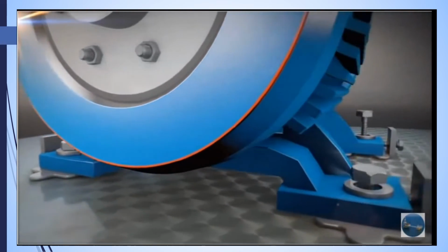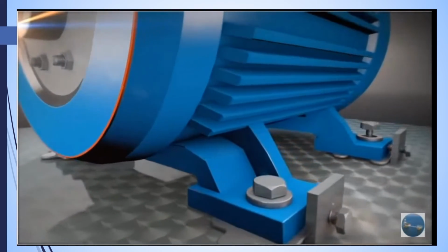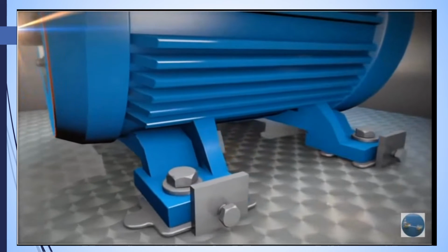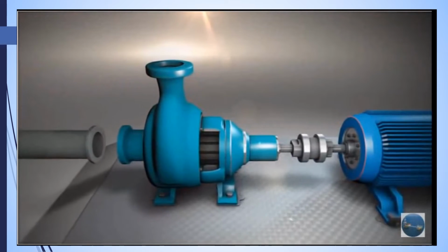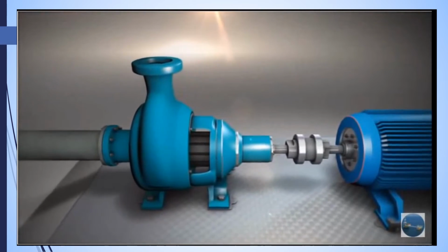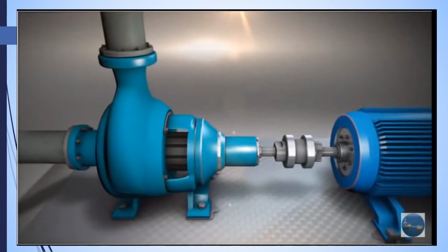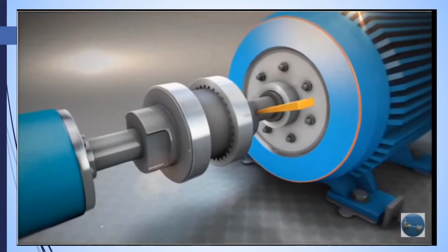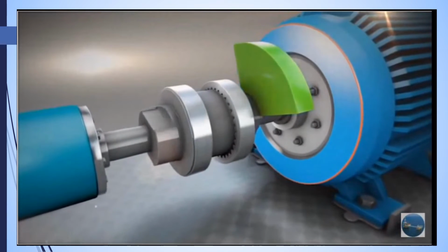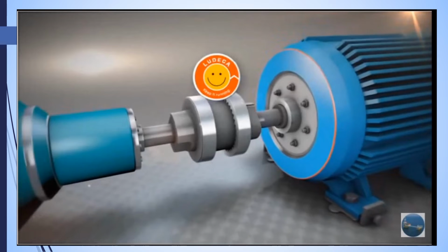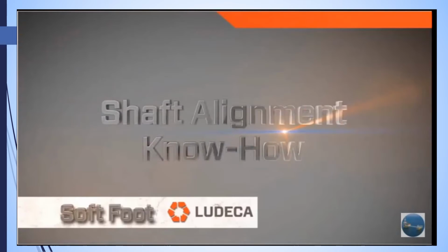Likewise, all pipe fittings should be completed without imposing any stress on the machines. When machinery is properly installed and given reasonable maintenance, the asset's operating life should meet or exceed its life expectancy. A precision alignment of the machines to proper tolerances is required before releasing the asset to operations and be put in service.